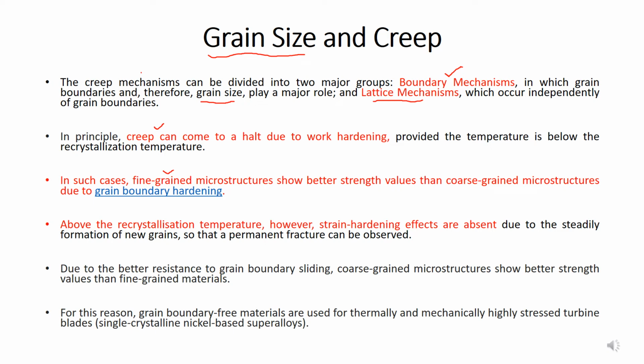As the grain boundary also serves as a hindrance, at low temperatures the dislocations are difficult to move, and these are also stopped by the grain boundaries, meaning the movement of the dislocation is also stopped by the grain boundaries. Because the temperatures are low, grain boundaries cannot move, and those grain boundaries are also helping the dislocations to stop moving, which in turn is reducing the creep.